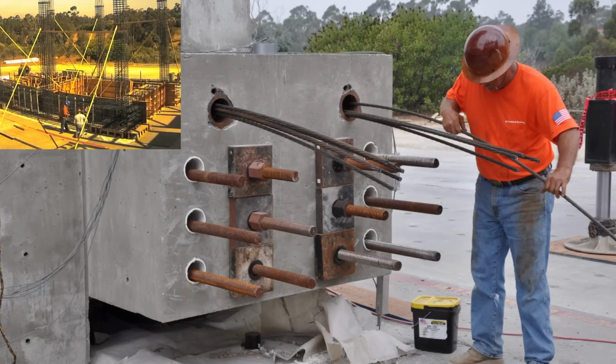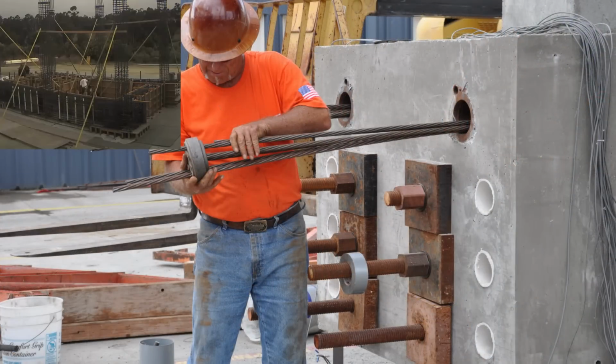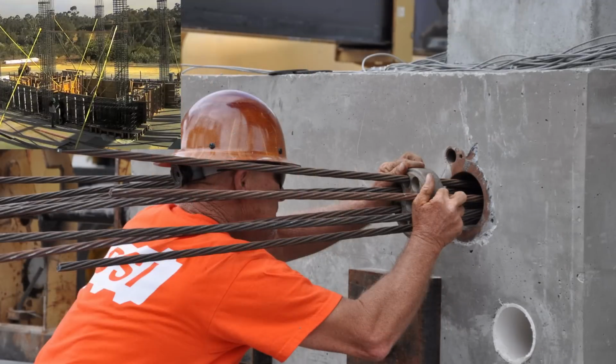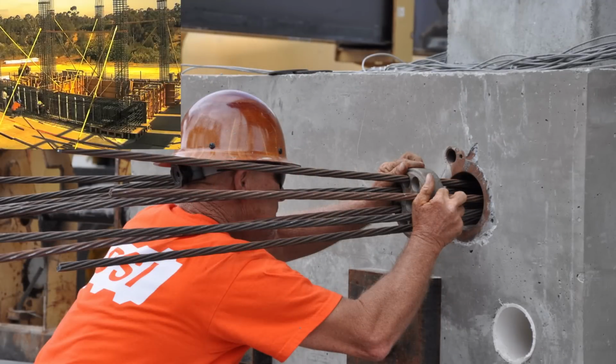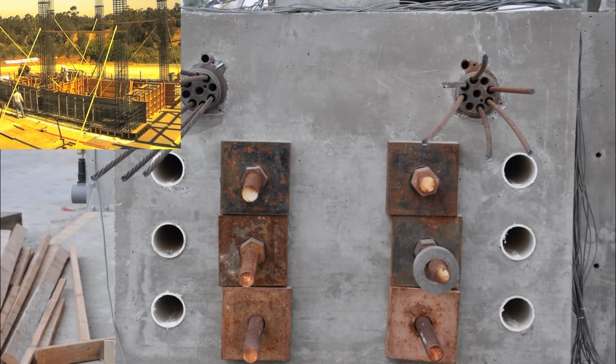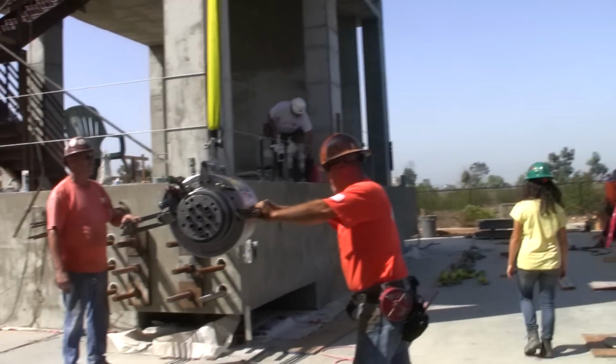Post-tensioning is the placing of voids or ducts into the concrete before the concrete cures. High-strength steel tendons are inserted through the pre-made ducts and the concrete is poured around them. When the concrete hardens, the tendons are stretched or tensioned by hydraulic jacks to their desired force level. Anchors are placed on the tendons and the loading forces on the cables are released, resulting in a transfer of their tension forces into the concrete block.